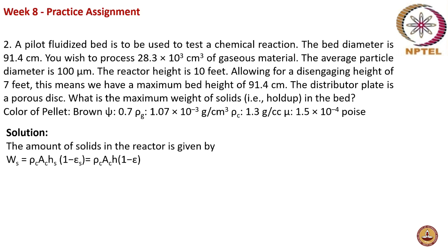Just imagine you have some glass beads, and you're packing them in a measuring cylinder. Will it have porosity? Before I pass the gas, will it have porosity? Yes, it will have porosity, right? Even if the bed is fixed, since you are arranging multiple particles, it will have its own porosity, correct? That is why even in packed bed reactor design, you estimate the term called porosity of the bed, correct?